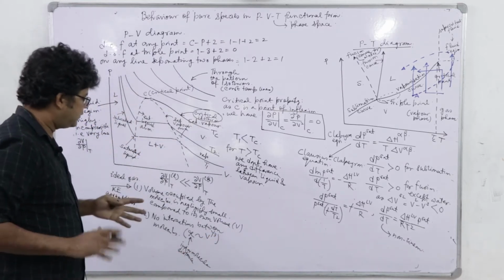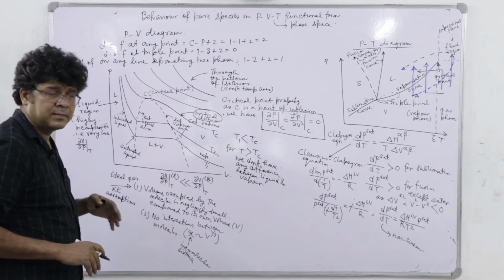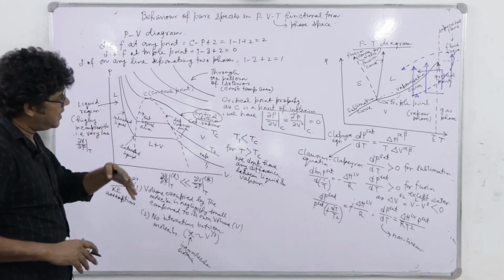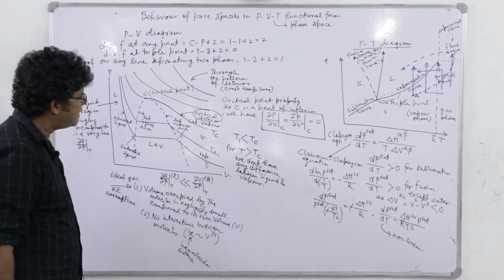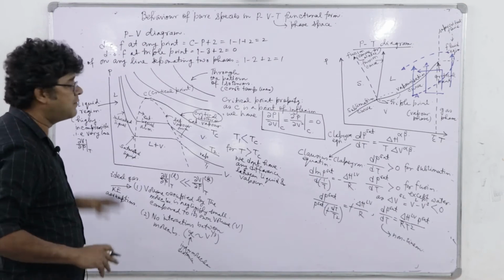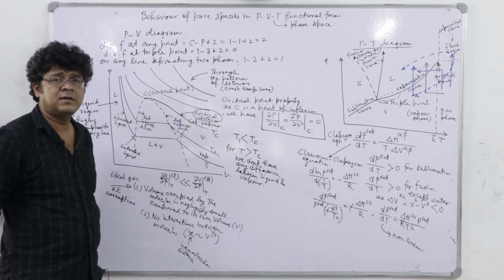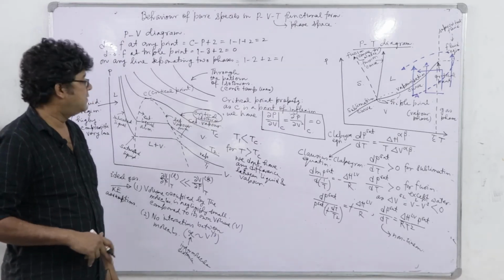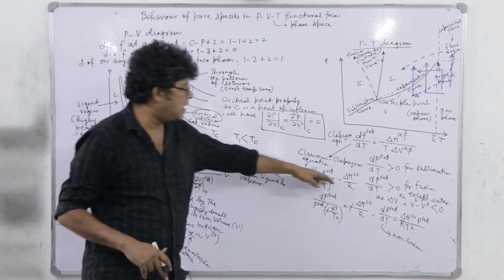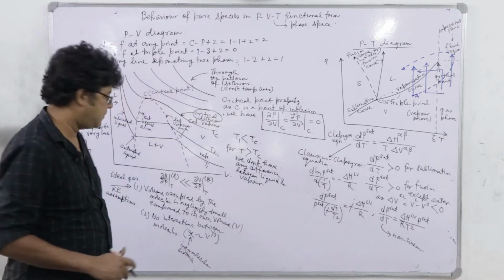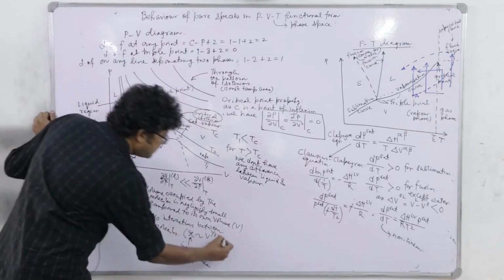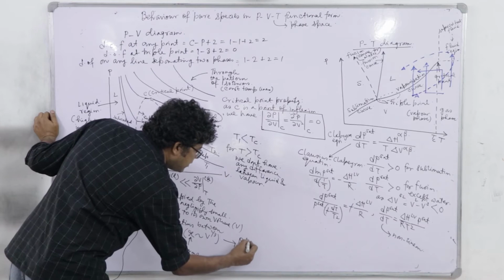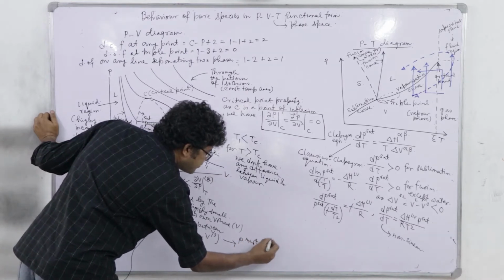Right. So, for an ideal gas model, which the real gas will actually tend to, we must have a very high volume. That means respectively a very low pressure according to the nature of this PV space. So, the pressure must be low,